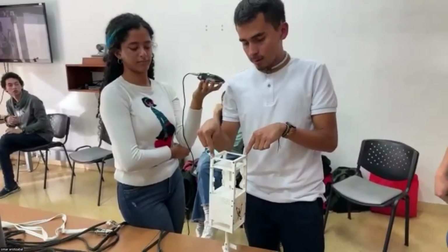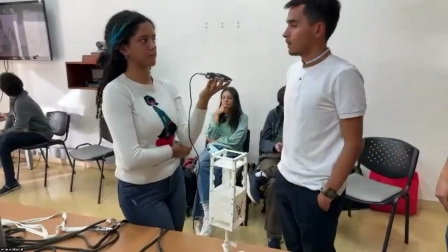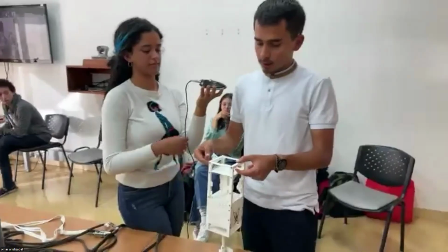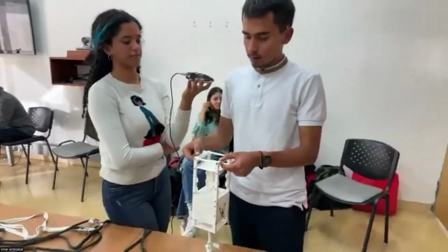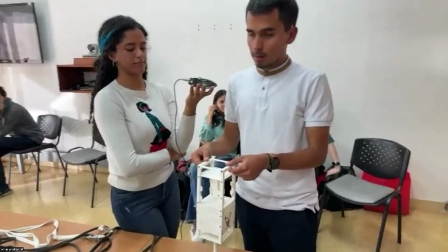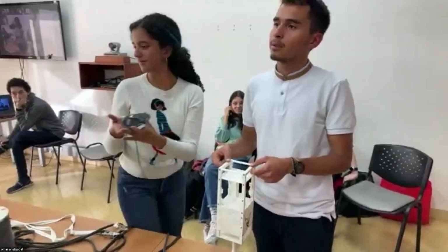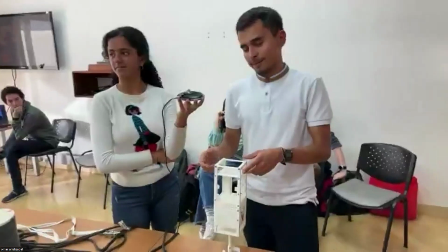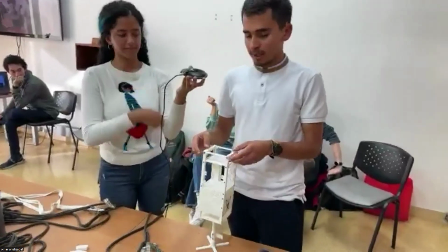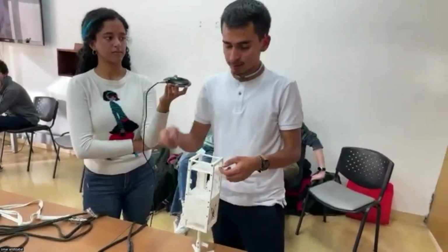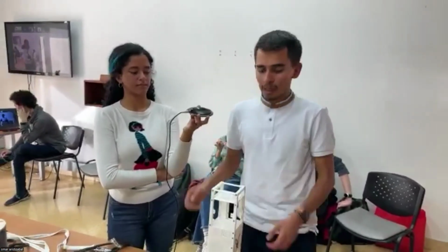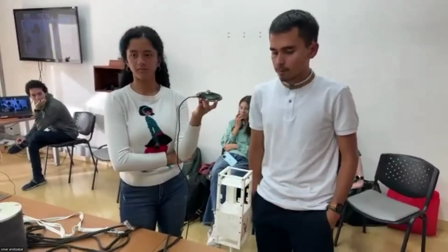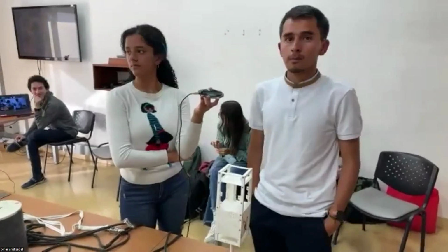Okay. And then did you analyze the bolts that you have in those locations at all? Bolts of this CubeSat? Yes, like if the bolts would shear under that force. We're still making the analysis. It's still in progress, the analysis in terms of deformation, bolts, and stresses for the payload. Okay, but make sure to check the bolts, since that would be sort of your weakest link in this frame.